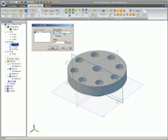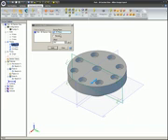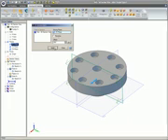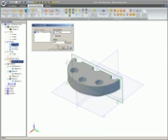For the slicing plane, you will need to select the face or plane you want to use. The arrows indicate the portion of the material that will be left on the screen. Everything behind the arrows will not be shown. If the section view is going in the wrong direction, just click on the reverse icon. If you wish to offset the slicing plane a certain distance from the selected plane, that value can be inserted in the Offset text box.